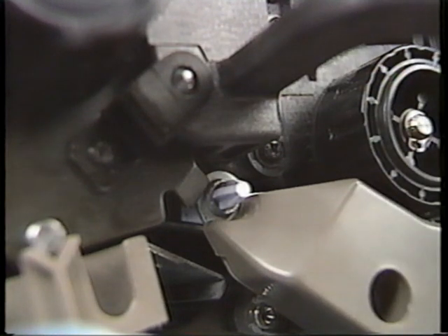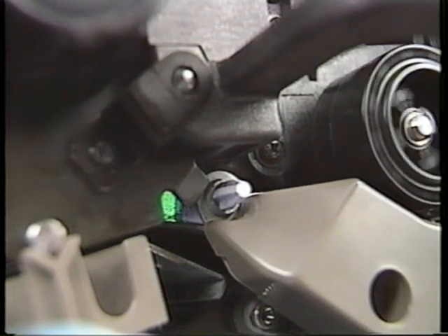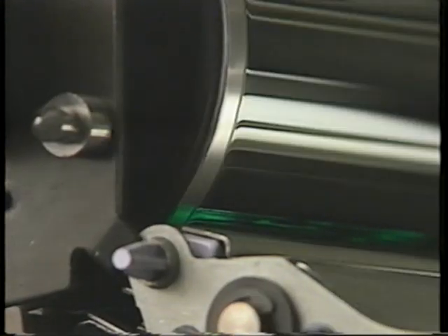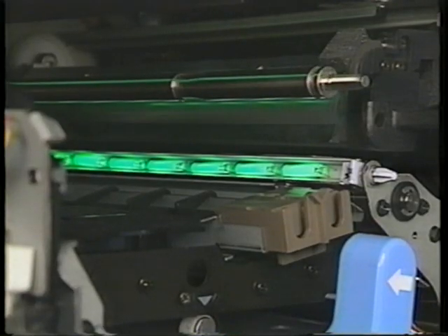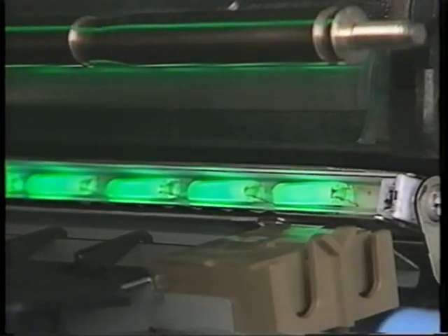Rather than reducing drum charge, some copiers avoid this problem by using a pre-transfer lamp, positioned close to the photoconductor between the transfer corona and the development unit. Light from the pre-transfer lamp reduces the latent image charge and therefore weakens its attraction. Not enough to cause the toner to drop off, but enough to assure an effective transfer. Reducing the drum charge also prevents toner particles from being attracted back to the drum during separation.